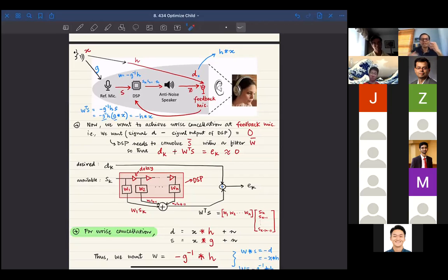The DSP is anyway multiplying SK with EK all the time. And once the EK is 20, DSP multiplies EK with SK, figures out what is WK plus 1, changes W. That gradient descent is actually continuously happening. So once EK goes up, W shifts. You bring down EK.